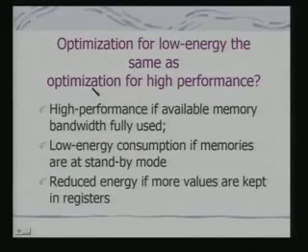So let's take an issue example later on, we shall look at them. Here we are looking at the trade-off between optimization for low energy and optimization for high performance. High performance is available if memory bandwidth is fully used, and low energy consumption if memories are primarily at standby mode, and reduced energy if more values are kept in registers.